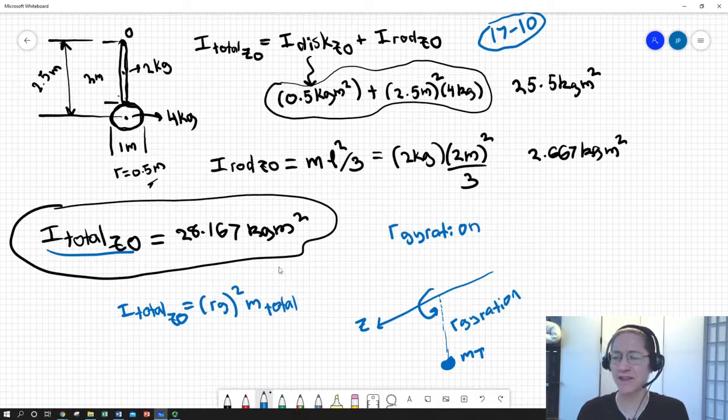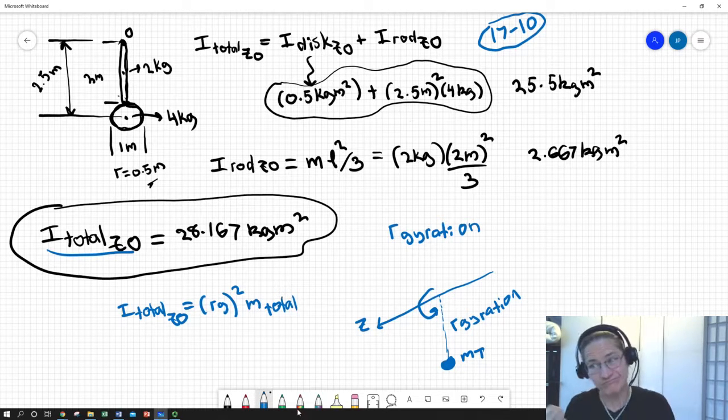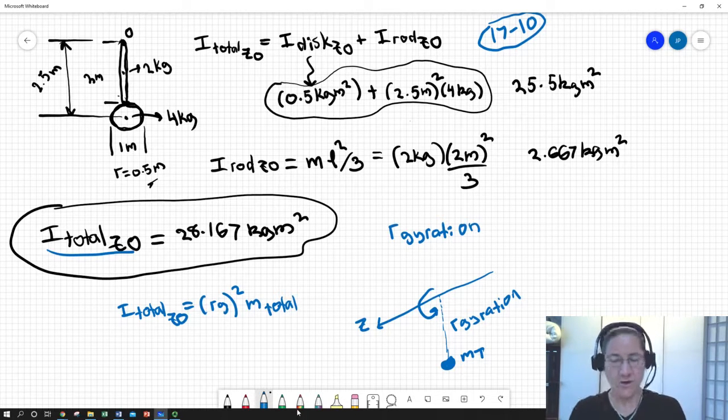So it's a little bit like the parallel axis theorem, except we put all the mass in one place, so to speak. Kind of similar there. And it uses the same properties of integrals, except in this case it takes all the mass and sticks it in one location. So very handy if somebody has already, say, calculated the mass moment of inertia, and maybe we're changing density or something. So the distribution of mass is the same, but the total changes.